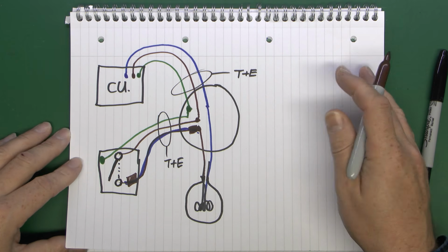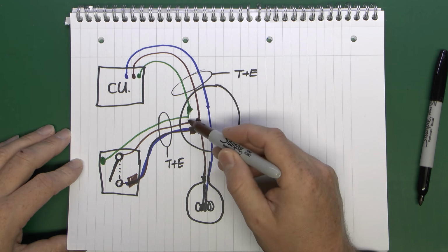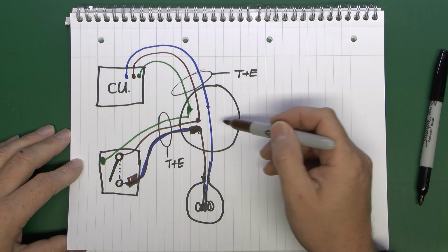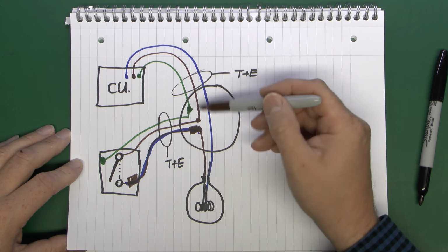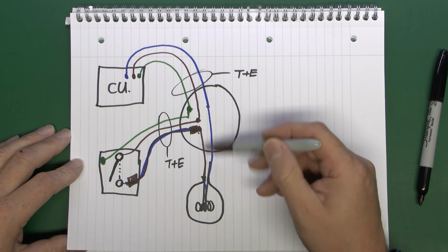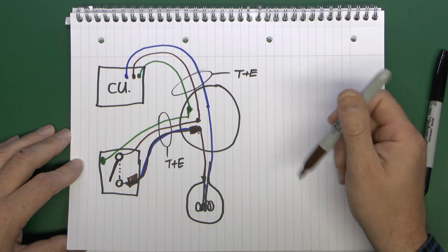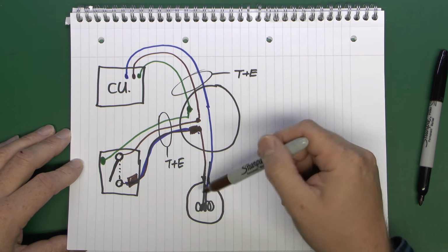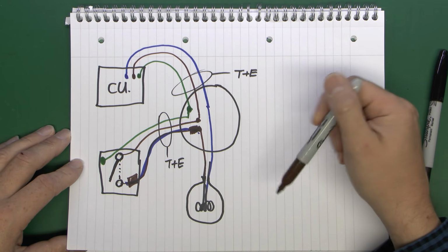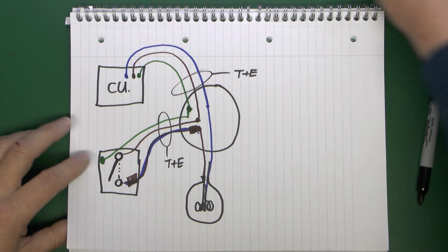Now this is fairly untidy, but a real ceiling rose of course has terminals inside, which are for all of these various connections here, because the neutral doesn't actually come straight through to the lamp here. There are obviously connections inside, otherwise you'd have to have a ridiculous piece of cable which somehow had branches and things coming out the side of it. So the real kind of ceiling rose looks more like this.